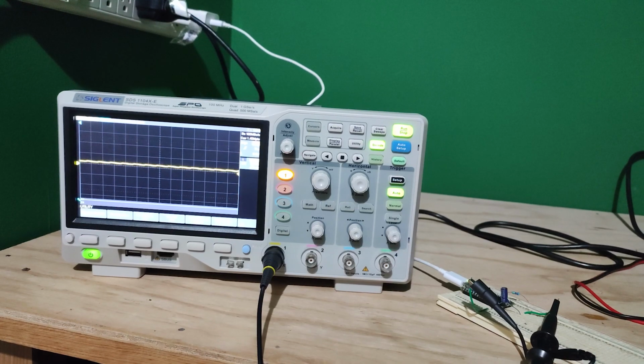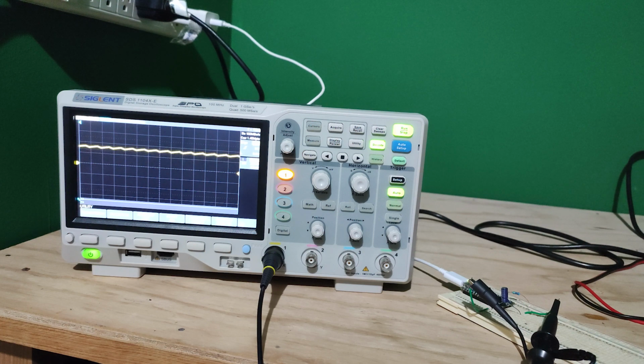And now we can see an application of converting the PWM signal to a linear voltage signal. Applying a low pass filter, we can filter the low frequency, which is going to be a linear signal, technically linear, and we can see how it is now a linear signal in the oscilloscope. So we can have the PWM as a DAC, for example, or to control any linear application. So now we have the capability of linear output with a microcontroller.